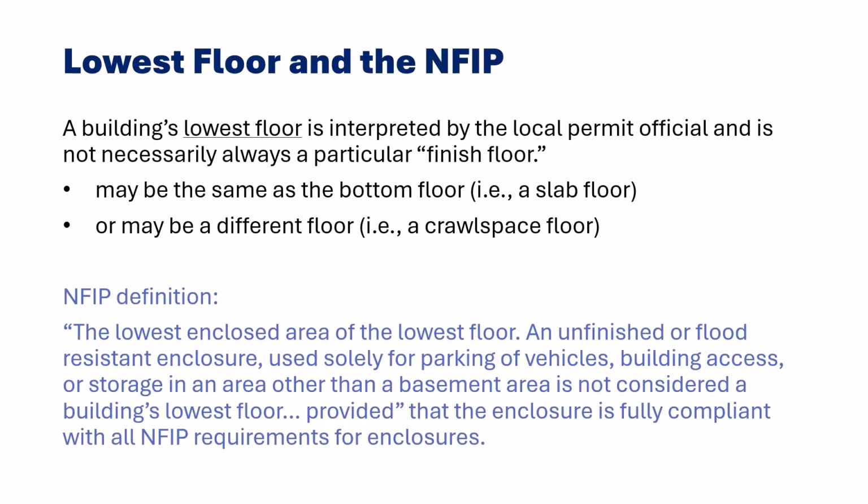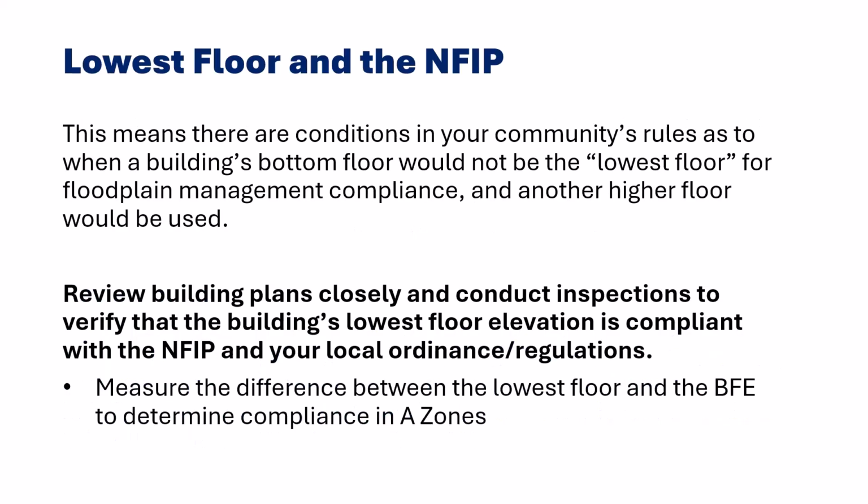An unfinished or flood-resistant enclosure used solely for parking of vehicles, building access, or storage in an area other than a basement area is not considered a building's lowest floor, provided that the enclosure is fully compliant with other NFIP requirements for enclosures. This means that there are conditions in your community's rules as to when a building's bottom floor would not necessarily be the lowest floor for floodplain management compliance.